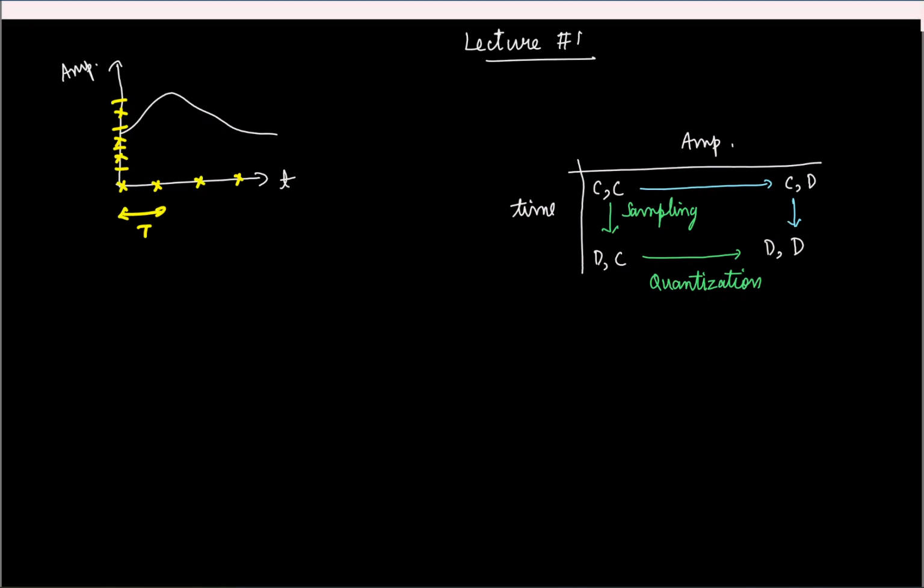And of course, you'll also want to convert from digital to analog, so you can do something similar. These circuits, which deal with conversion of signals from one domain to the other, are called data converters. The one that converts analog to digital, I'm sure you know, is called an analog to digital converter, ADC, and this is the symbol for the ADC. The analog signal is the input, so it's just a single channel, one line. The output is digital, so we'll have a fat line there, as there are multiple digital bits. Similarly, the DAC is a digital to analog converter.